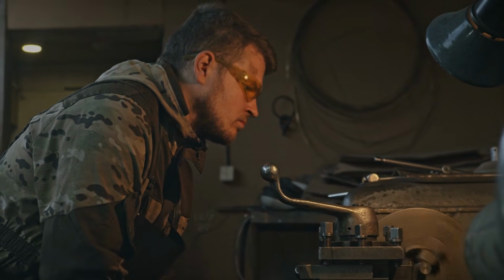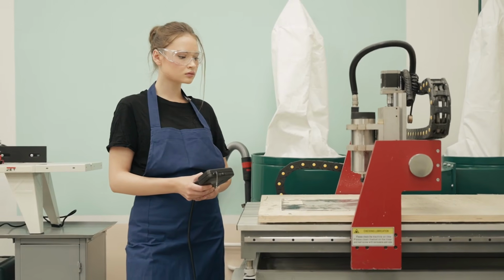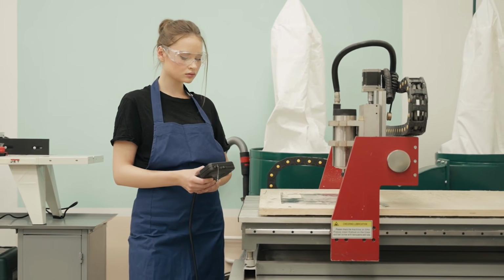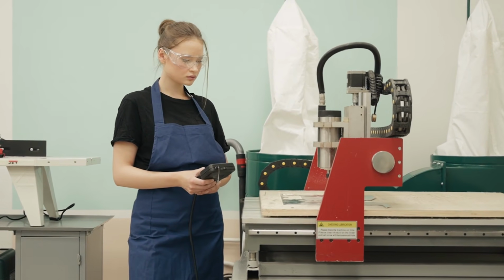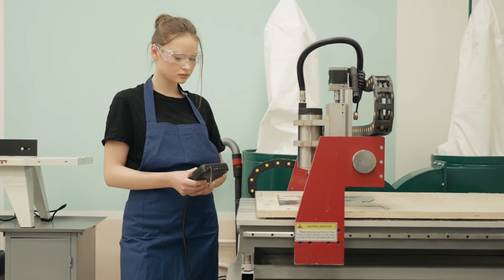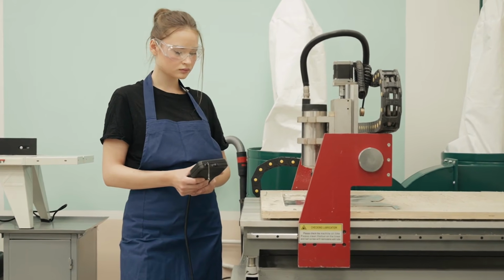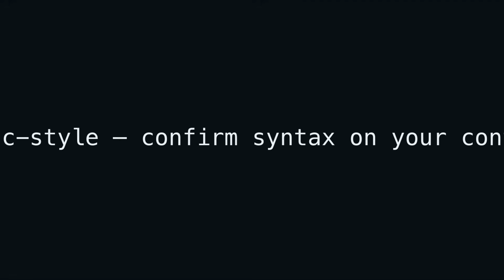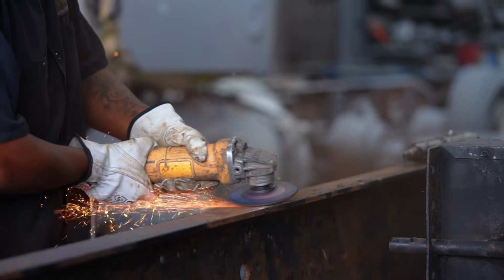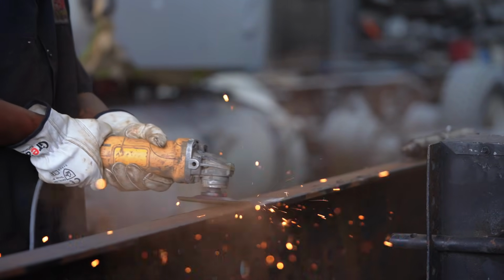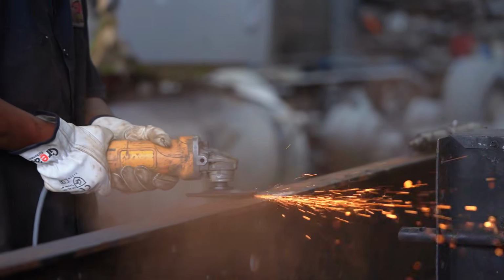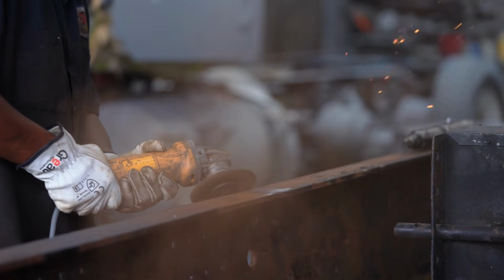Then it leaves. That's what G50 is for. On most Fanuc-style controls, G50 with an S value clamps the spindle. CSS can ask for more. The clamp says no. It looks like this: G50 S2000, then G96 S400. CSS can run wild until RPM hits 2000. If your program runs G96 without G50, you're trusting the geometry to never get small. That trust is what dented the shop wall.